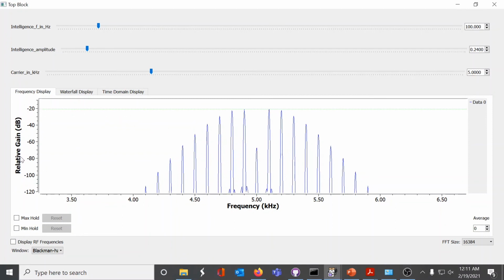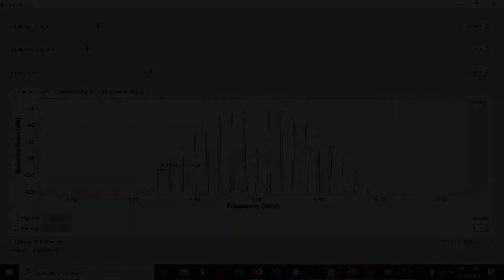Once again, this is on a dB scale. So if you talked about a signal that was 80 dB down, which is basically this point here, you might say that this is not significant. You might say this is not significant. At some point, these signals would be below what we call the noise floor, and at that point, they're just not worth talking about anymore. Speaking of noise, hold that thought because we're going to come back to it in a week or so.